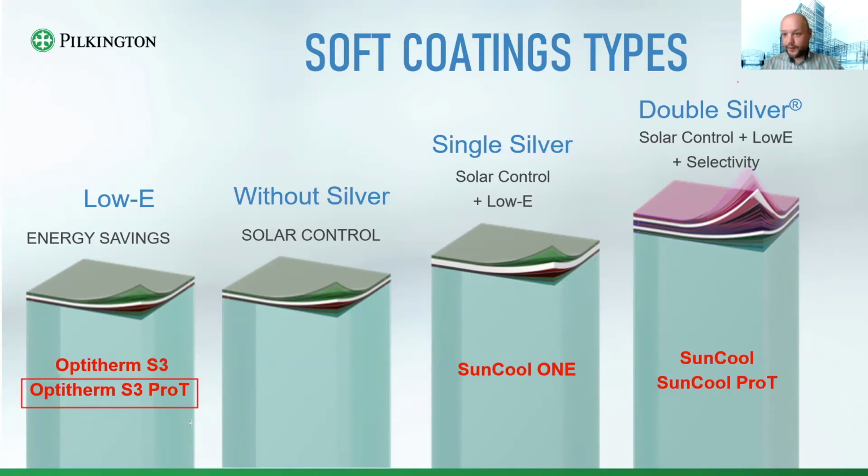So T means tempering. Our competitors, almost all of them, also have some kind of T letter involved in the name. So not much difference here. Annealed versions cannot be tempered because the coating will die during the tempering process. On the contrary, temperable coatings have to be tempered in order for them to achieve their characteristics, because before tempering, their characteristics are usually worse than after.